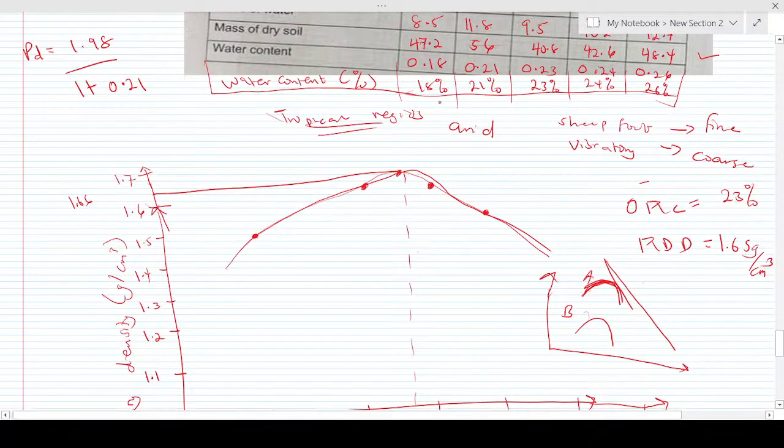Now from this equation, this is the last thing I want to talk about. I should have said this when we were talking about stress. From this equation, effective stress is equal to total stress minus pore water pressure. What this means is that if there is an increase in pore water pressure, then the effective stress is going to decrease. And pore water pressure is a function of groundwater, so when more water enters the soil, pore water pressure is going to increase.